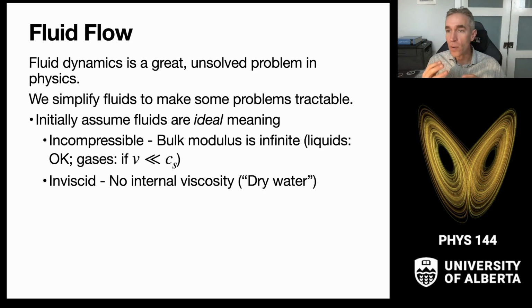And what we're going to do is work primarily with ideal fluids, and those ideal fluids are going to be incompressible and inviscid. Incompressible means that their bulk modulus is basically huge, practically infinite. And so if I push pressures on them, their volumes aren't going to change. Their pressures can change, but they're not going to change their volumes here. For liquids, this is pretty good. We saw that the bulk modulus of water was somewhere in the tens of gigapascals.